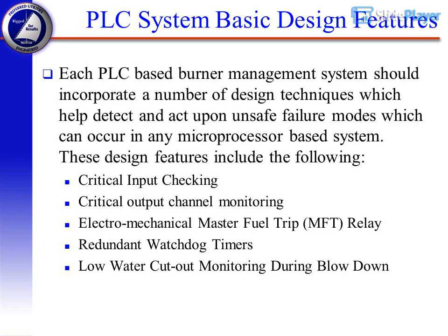PLC system basic design features. Each PLC-based burner management system should incorporate a number of design techniques which help detect and act upon unsafe failure modes which can occur in any microprocessor-based system. These design features include the following: critical input checking, critical output channel monitoring, electromechanical master fuel trip (MFT) relay, redundant watchdog timers, and low water cutout monitoring during blowdown.